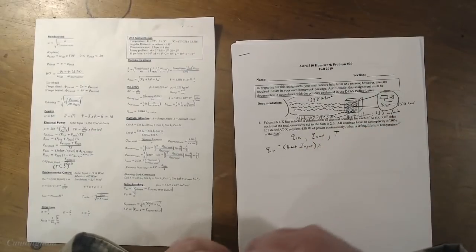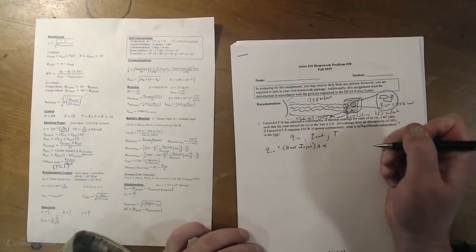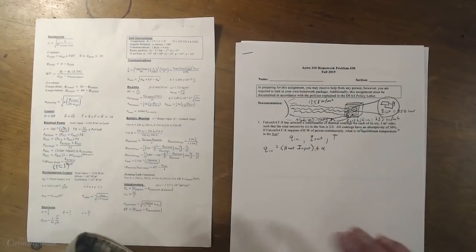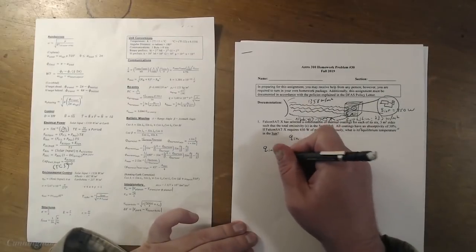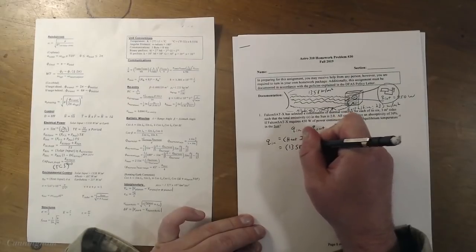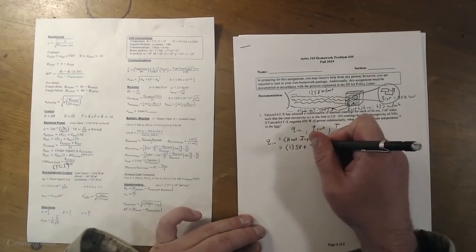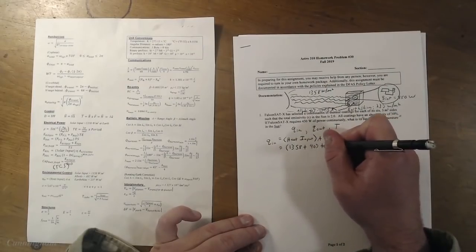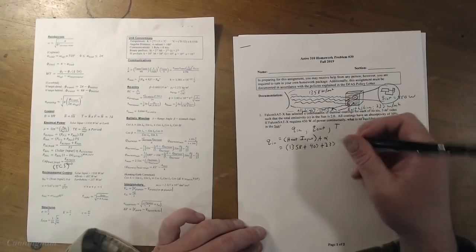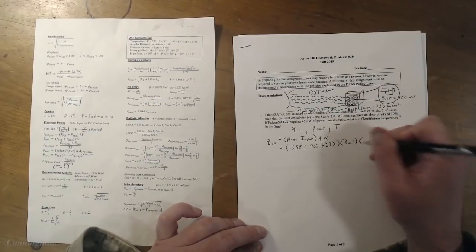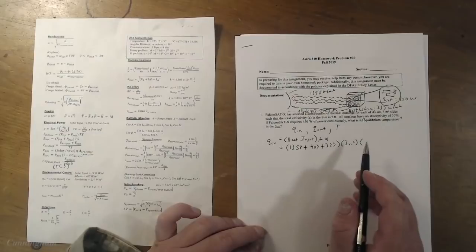So the area of one side, multiplied by this thing called absorptivity, which is basically how much of it FalconSat sucks up and holds on to, versus how much gets bounced back out or retransmitted. Okay, heat input. Let's begin with that. What kind of heat is coming into the satellite? Well, we have 1,358 watts per meter squared from the sun. We have 407 watts per meter squared from albedo. We have 237 watts per meter squared, double checking those numbers, from Earthshine. The area of one side is 3 square meters. And the absorptivity, they tell us, yep, is 30%.